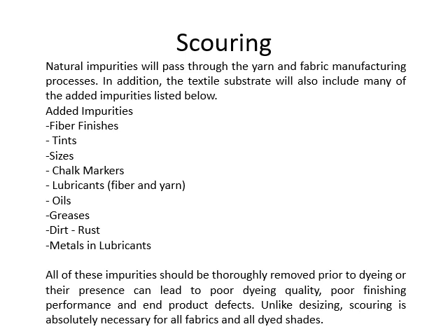However, companies often use a quick method where a few drops of clean water are placed on the dry scoured fabric surface. The time taken for the drop to be absorbed is recorded, and normally clean scoured fabrics should absorb the water in 1 to 3 seconds. This test is also called the drop absorbency test.